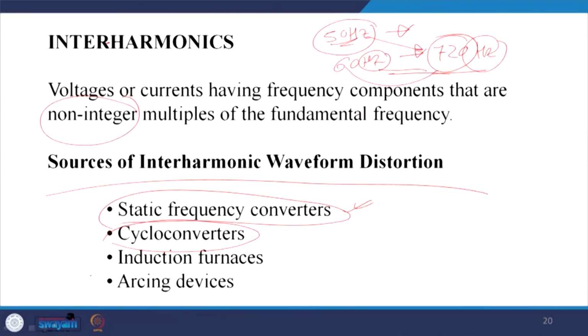Once you are converting, or you are having V by F control, this case also arises with the matrix converter. The same way for the cycloconverter, for the little higher power devices, because of induction furnaces and arc devices, this may lead to interharmonics.